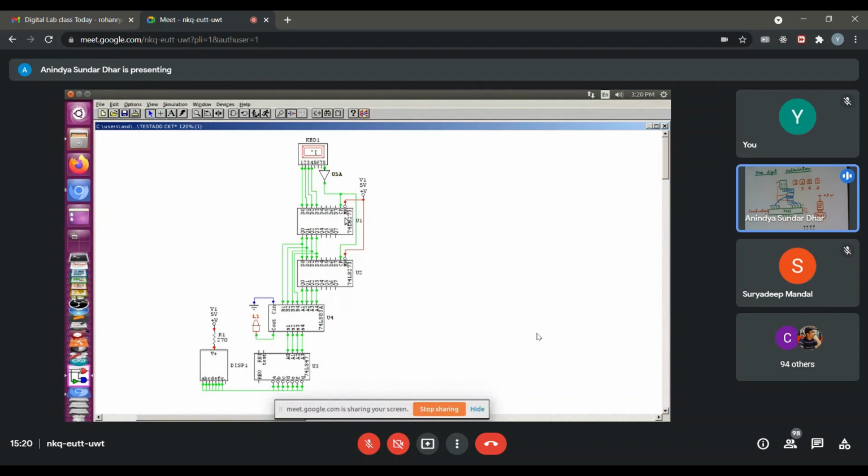So what could be the purpose of that? Rather than living with the garbage value, whatever we just mentioned, I can, if I wish, reset it. For this case, I do not need to reset it. So that is why I have connected both of them. They are active low, you see. I have tied them together and connected to plus 5 volt.